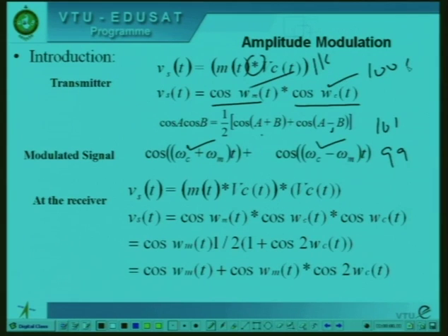By performing multiplication, one frequency that we get after modulation is the higher frequency, 101 kilohertz, and the lower frequency is 99 kilohertz. See how nicely the modulation, or the multiplication, gives us two frequency components, 101 and 99 kilohertz.